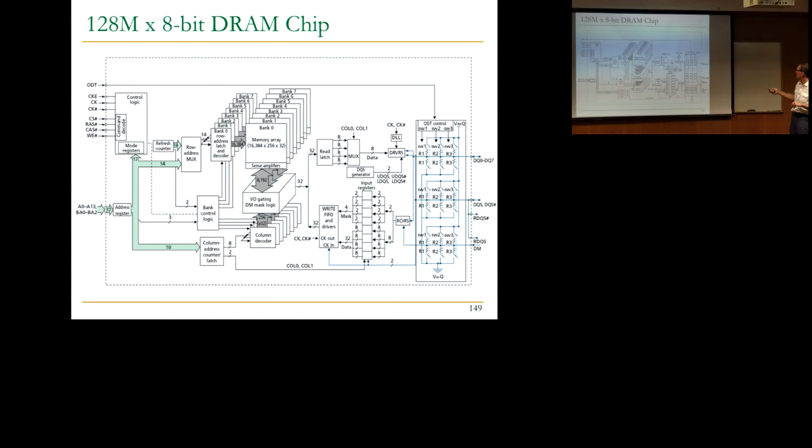As you can see, this has an 8-bit interface. But over here, this is not 8 bits. It's actually reading 32 bits. So it's doing internal prefetching inside. Why is it doing this prefetching? Because it's using this burst mode. Every cycle, it can give you 8 bits, and you can do this for 4 cycles. As a result, it reads 32 bits, buffers them, such that it can give you 8 bits every cycle for 4 consecutive cycles. That's how you get 32 bits out of this chip in 4 cycles, because it has read 32 bits.